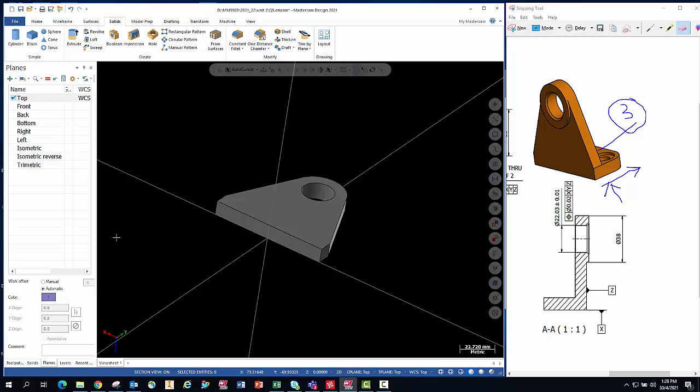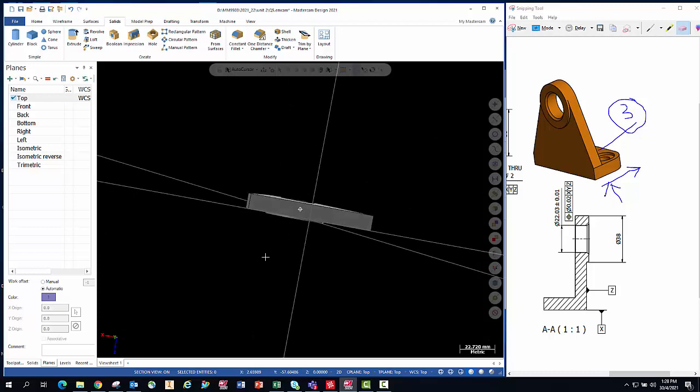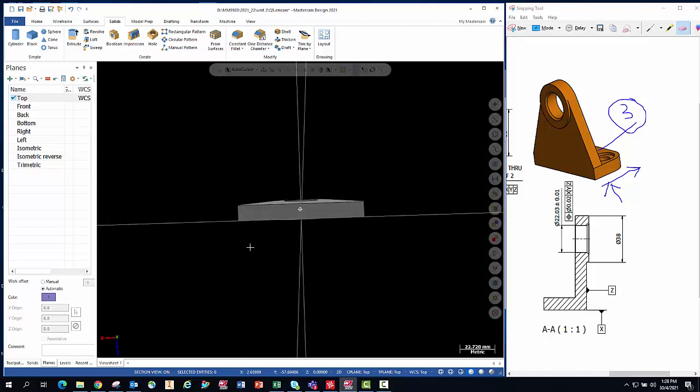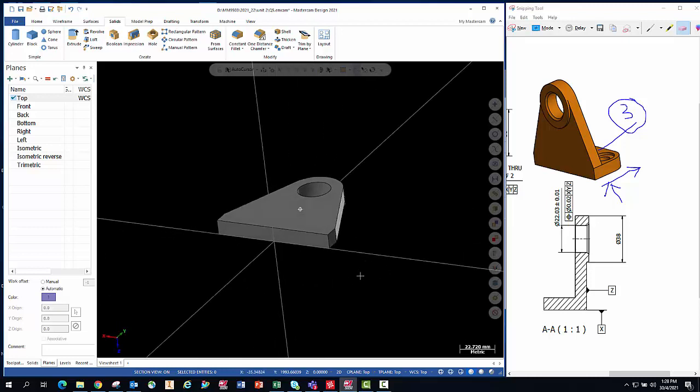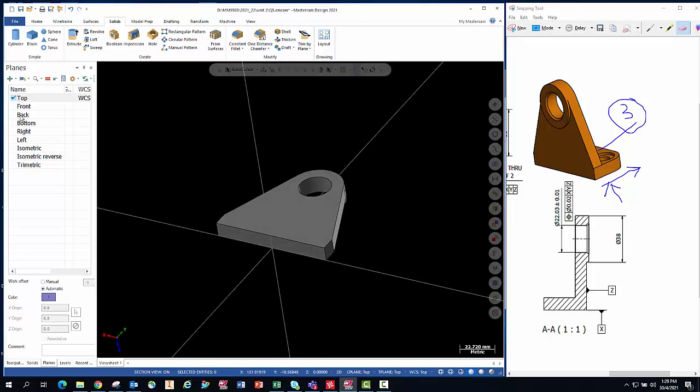In the case of our sketching plane, we can specify any of the existing surfaces and orient them accordingly. So at the end of the day, I like to sketch somewhere in this direction. Now let us see how we can do this. We go to the plane and select to have it from solid surface. This is my sketching surface.